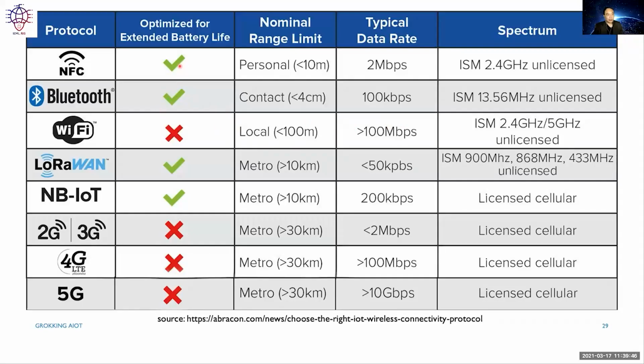Right, the other thing that we would want to consider is the power requirements. For many devices, we do not want a permanent supply connected to the grid, or it's not possible to permanently supply it from the grid. So we need very low power transmission so that the batteries on the device do not have to be replaced very frequently. This is the case where we want to use technologies like Bluetooth Low Energy. It's not really that slow, but in terms of power consumption, it's very low.